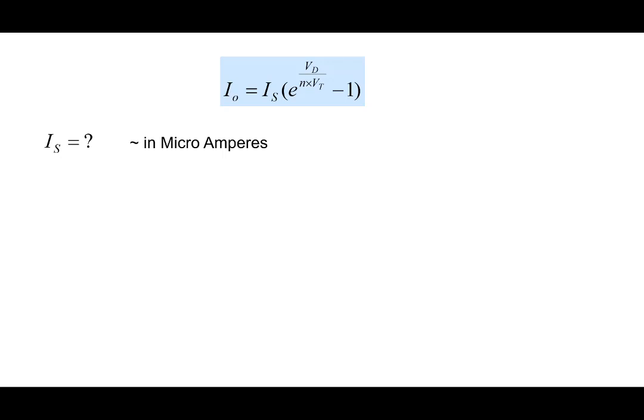I_s in microamperes. And obviously, when we ask what is the typical value of V_d, that is also 0.7 volt. One of the most common values of diode voltage that we offer is 0.7 volt, and for I_s, we say microamperes. Obviously, a very quick calculation will show you that these are inconsistent.